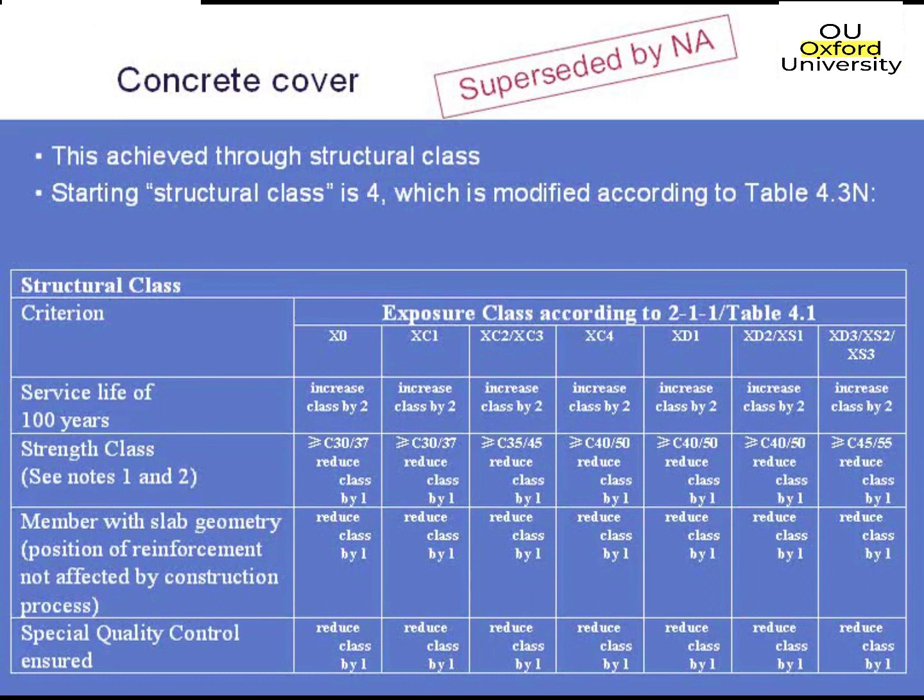Dependent on the strength class that you've got, you can then potentially reduce the structural class that you have. You then go on to look at whether you've got a member slab geometry or not. If you do have a slab, then you can further reduce your structural class. And then you look at the special quality control, and if you do have special quality control, you can further reduce that structural class if you needed to.